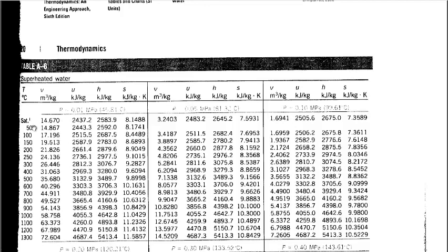Okay. Now you'll also notice that some of the subtables have blanks, right? So this subtable here doesn't have any data for 50 degrees Celsius. Why? Because water at a pressure of 50 kPa and a temperature of 50 degrees Celsius is a liquid. And we know that because the saturation temperature for water at 50 kPa is 81.32 degrees Celsius, but 50 degrees C is lower than 81 degrees, and so of course that would mean that it's a liquid. And so it's not a superheated vapor, so the data is not included in this table correspondingly.